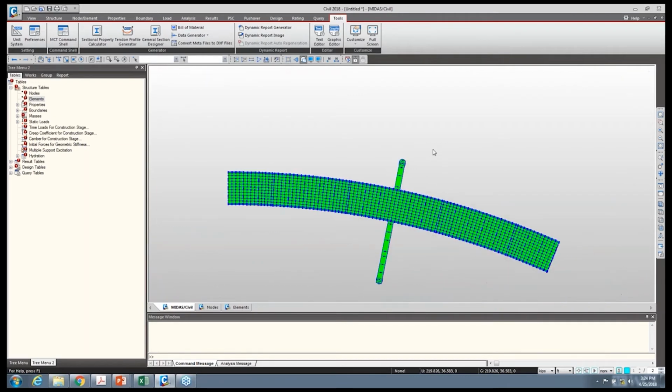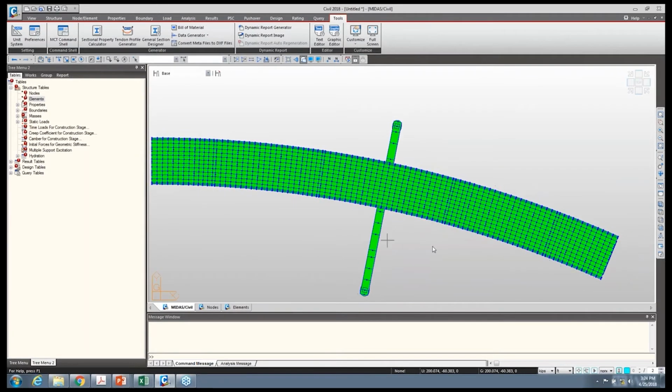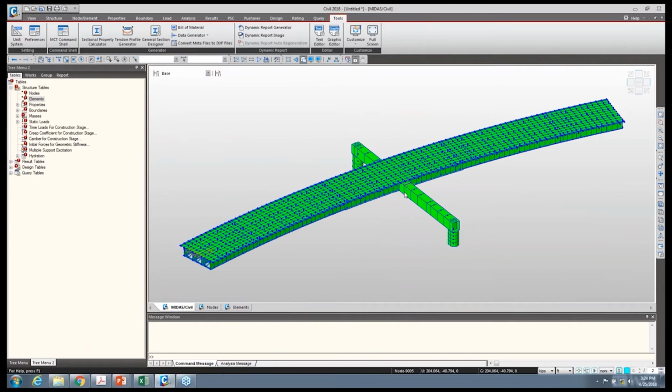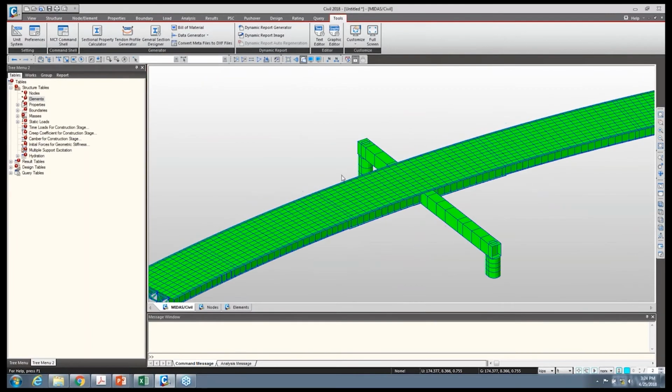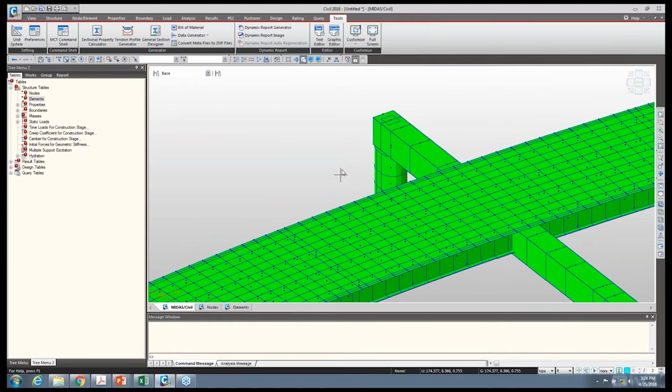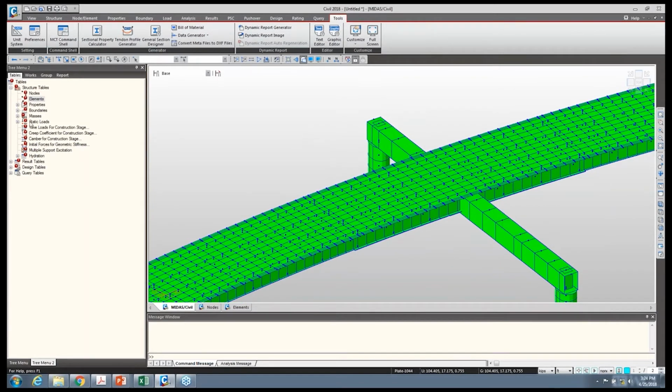And the way this can be done is we open up our boundary section and we select rigid link. And we can just go ahead and I recalled all these nodes by memory. But we're going to go ahead and make this left side a fully pinned condition. And we're going to make the right side a slider condition. So what you'll see here is I'm not going to select the Y direction. So as you see now, I have a rigid link.